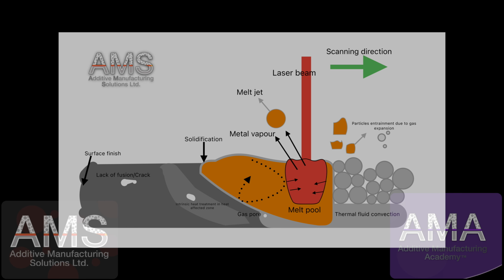That gives us issues. The issue with full remelt is that we are then having a melt pool. And in the case of a melt pool, similar to DED technologies, the ability of the material to resist the absorption of oxygen, nitrogen, hydrogen, or other nasties that are present in the technologies becomes much more problematic to prevent.